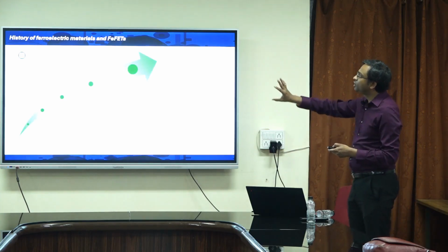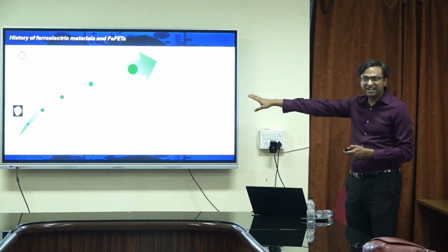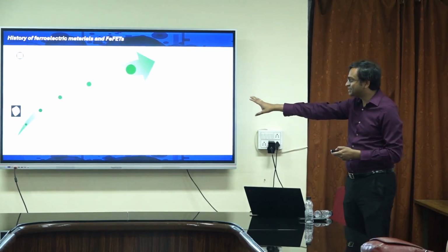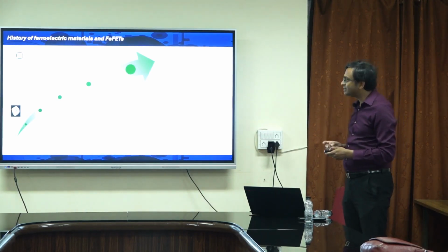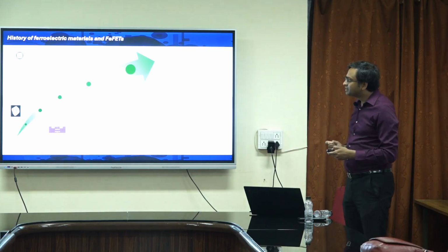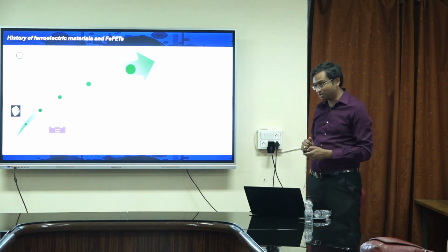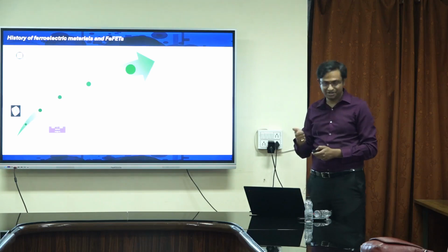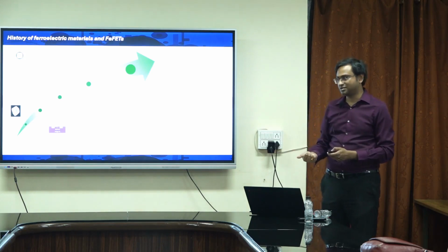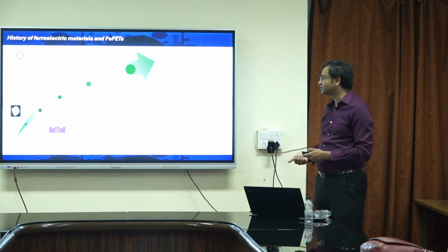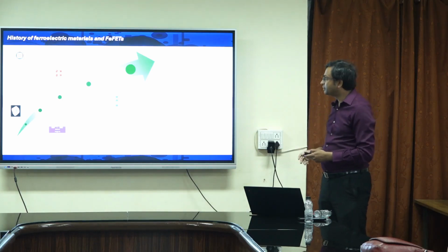But there is also a very long history of these ferroelectric field effect transistors. It goes back 100 years to when ferroelectric material was first discovered, right? Barium titanate, PZT were discovered almost 60, 70 years back, right? But the first FEFET was conceptualized in 1974. Still today we don't have an FEFET commercially available. It has been really an engineering challenge, a materials challenge, of how you grow these perovskites on top of these things. And then this could be used for neuronal circuits and stuff, which we'll probably come to.